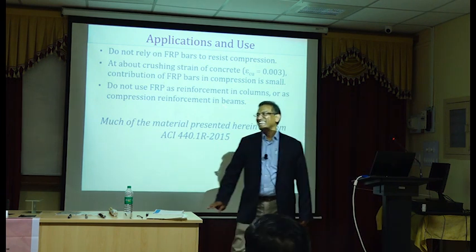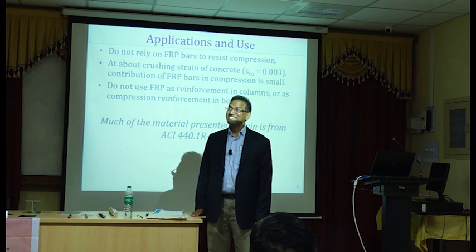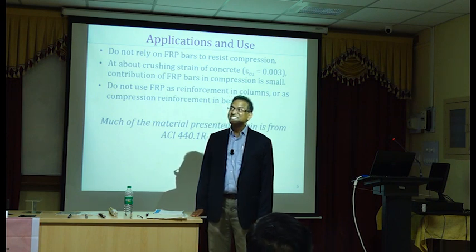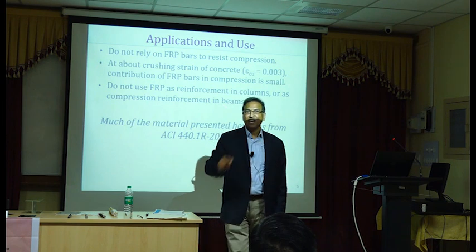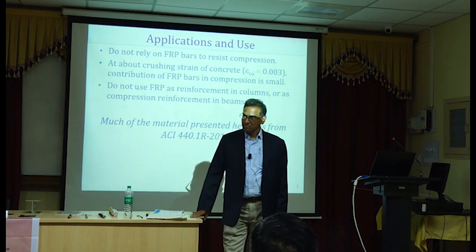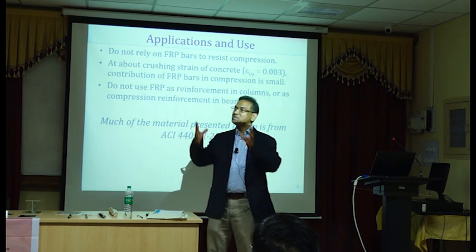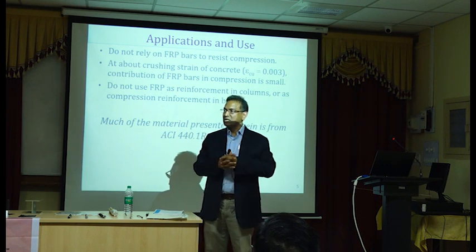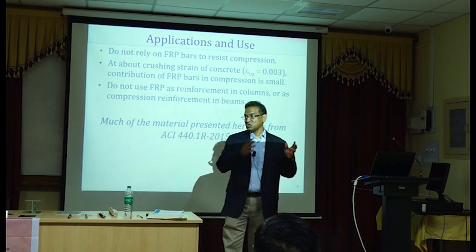But we are designing over design section. No. You are designing unsafe section. By considering cube strength. Am I right? I may be wrong. You tell me whether I am right or wrong. Sir, actually we are designing on overside as per the IS 456. No, you are using cube strength as the basis. This is not the actual strength in my view. Actual strength is the cylinder strength of concrete. Right. But what the standard says is use cube strength, right?